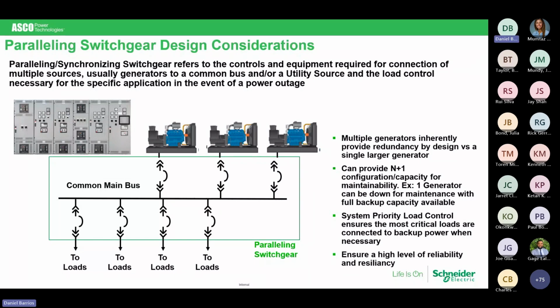When we are speaking about paralleling switch gear, okay, I really need you to work with the genset manufacturer's sizing criteria. And what I mean by that is you have to understand that when the first generator hits the bus, we are calling this dead bus arbitration, okay? We are going to have all 3 of the generator breakers open.